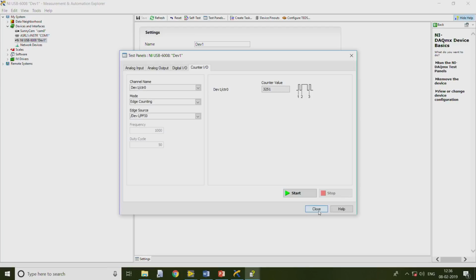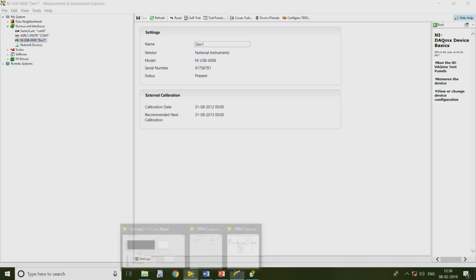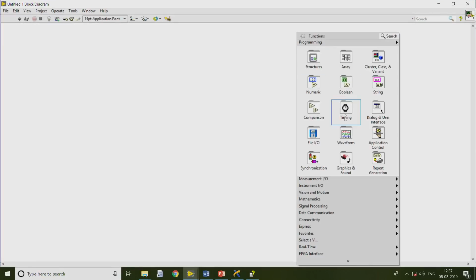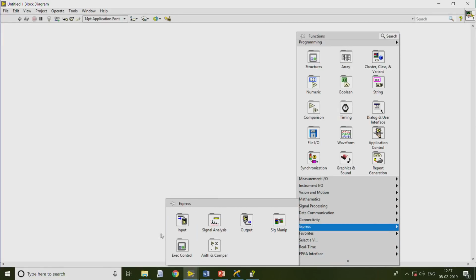So, what I will be doing is writing a code and providing voltage from software, so that depending upon the voltage, we will see in 1 minute how many pulses the motor is producing. For that, let me open LabVIEW. Since our intention was to record, I will be creating an Express VI to acquire the counter signals.